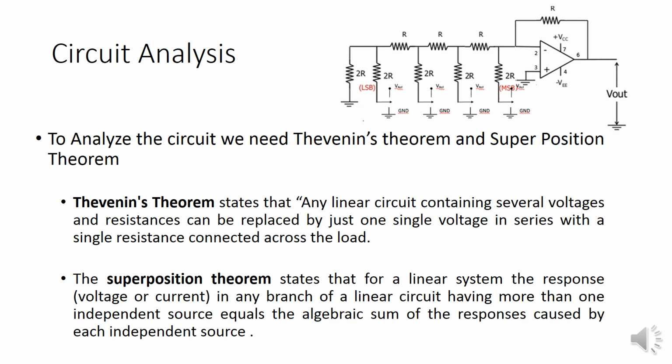To analyze the circuit we need two theorems. One is Thevenin's theorem and another one is the superposition theorem. Thevenin's theorem states that any linear circuit containing several voltages and resistances can be replaced by just one single voltage in series with a single resistance connected across the load.